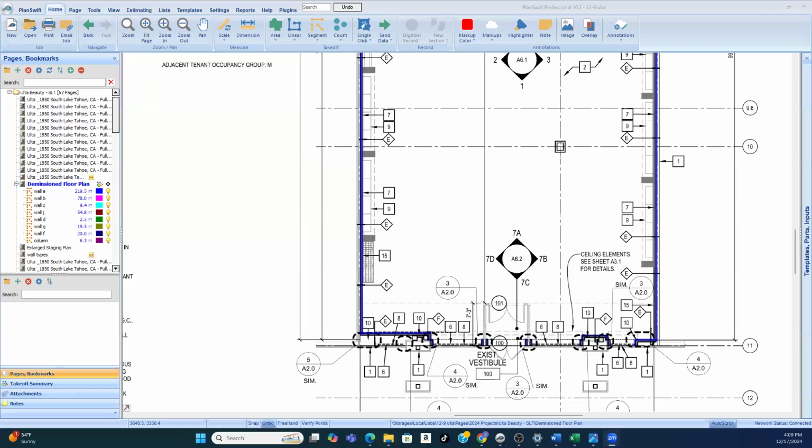That's the S plans. And then once we finish the S plans, assuming we already have the civil set. So let's go backwards. So if we have just dirt, we have the civil set. The civil set is everything outside the building. So once we walk outside, the civil set is what we see: concrete, asphalt, lights, underground sewers, curbs, gutters, parking lot stripes in the grocery store. That's the civil set. And everything underground, that's the civil set. So the civil set's all finished. Now we want to build the house. Then we start with the box. The box is the structural set.